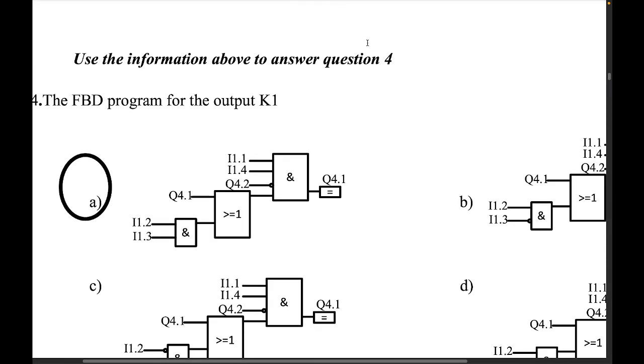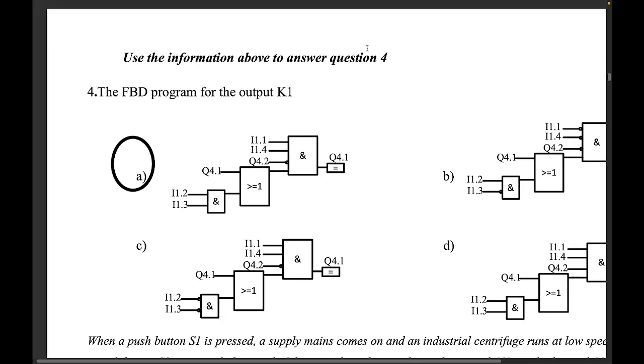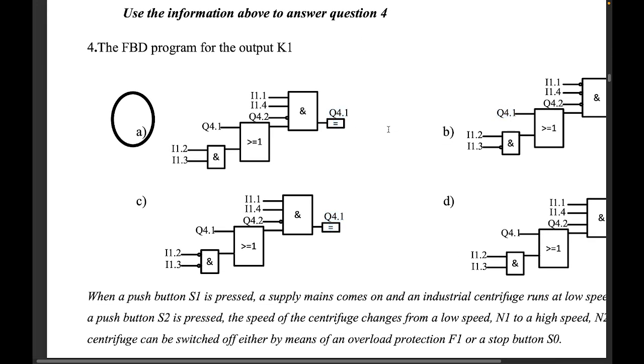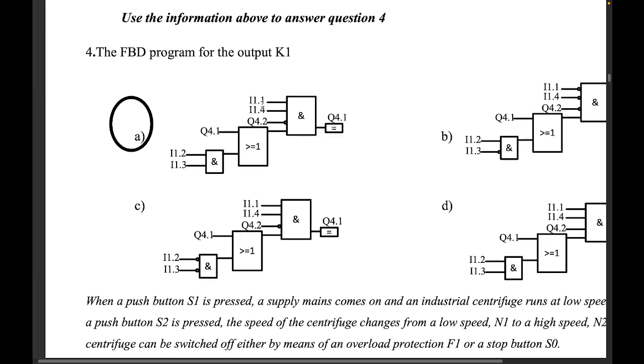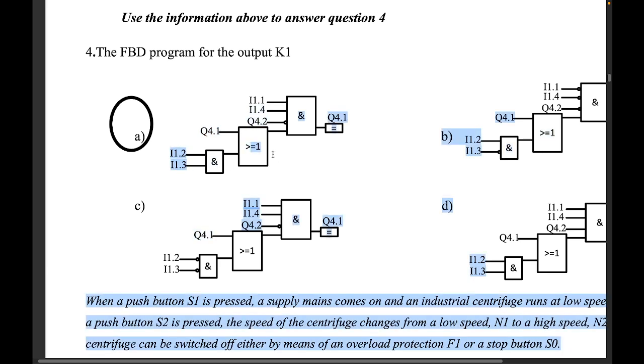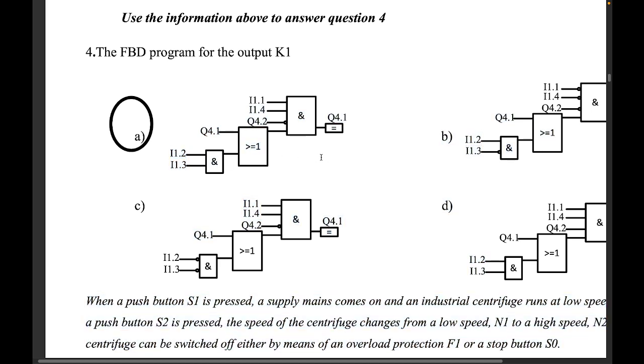So over here, the answer is A, as I've explained, right? So the stop should not be pressed, so the stop should be in the circuit. It should be 1; it should allow power to flow through. Overload should allow power to flow through. Reverse should be off, so it is negated. Then when I come here, either that small contact there is closed, or I press S2 and S3, and that's what will make current flow through. So the answer is A here.